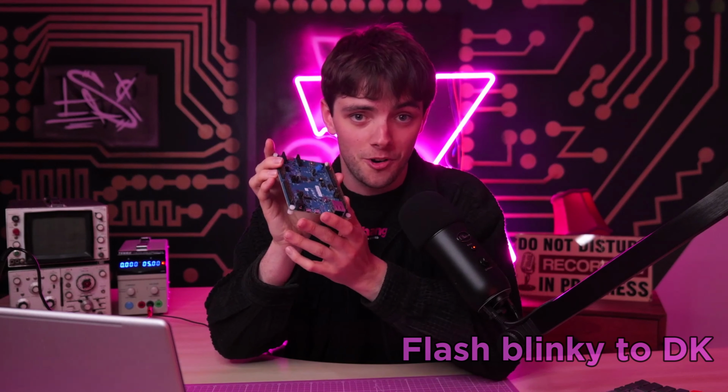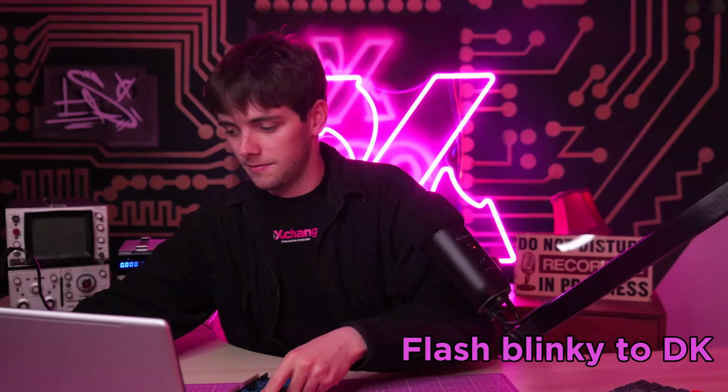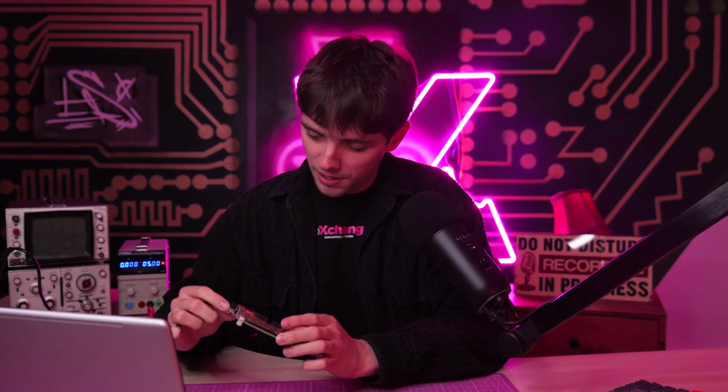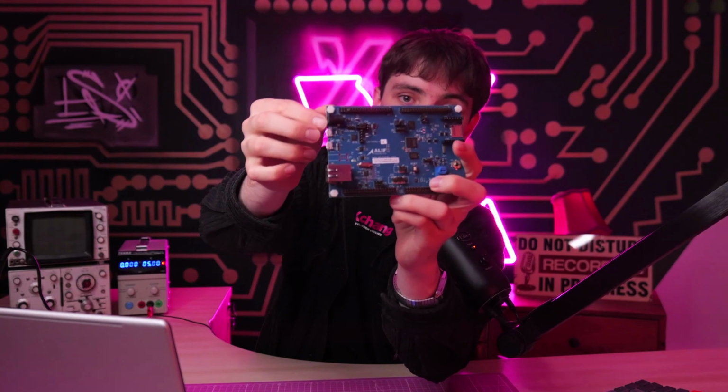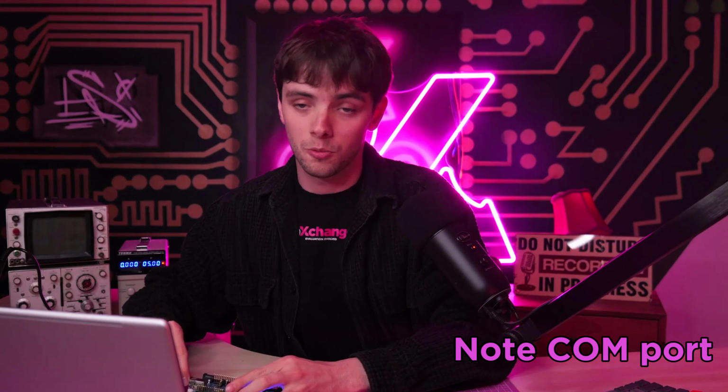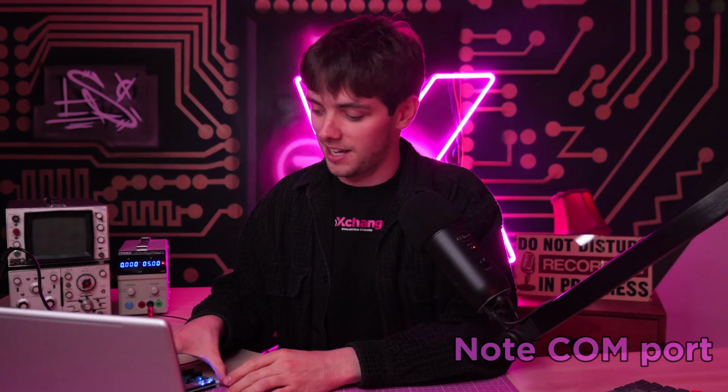Now it's time to program our board. We'll go ahead and connect it via the USB that we've been given. And we'll plug it into this port here. It says PRG USB. You'll find it. And if this port doesn't work, try the other one. Take a note of which COM this connects to as well, which port it talks through. You'll need that for later.